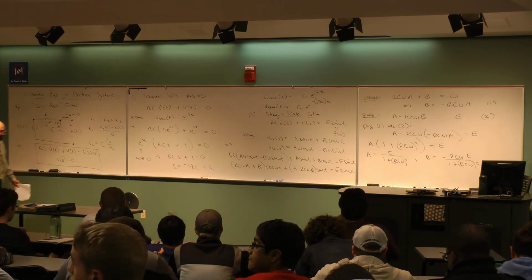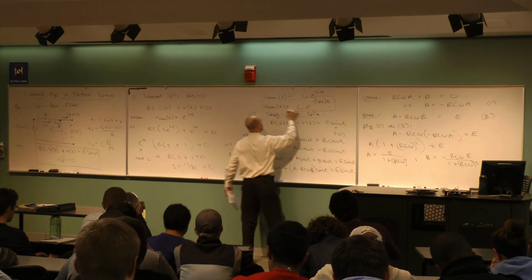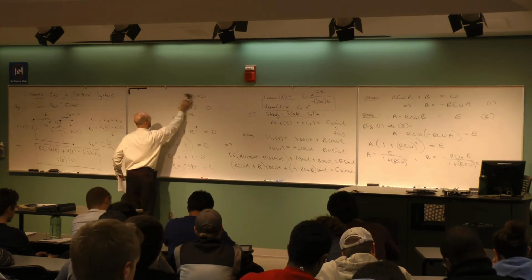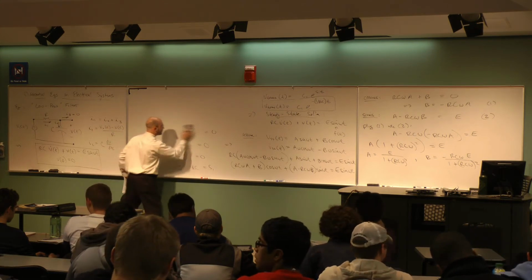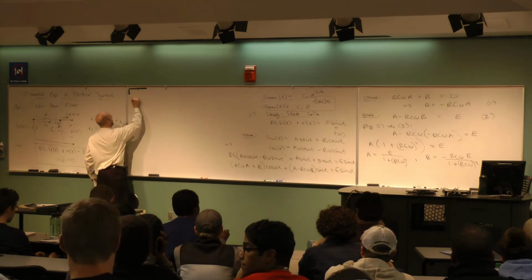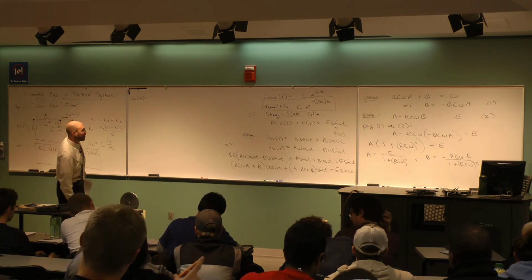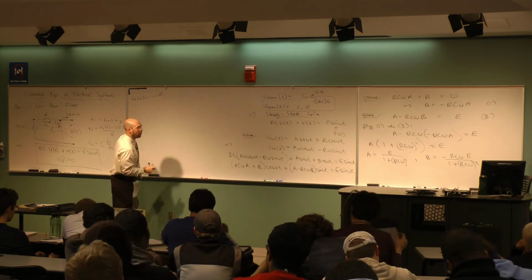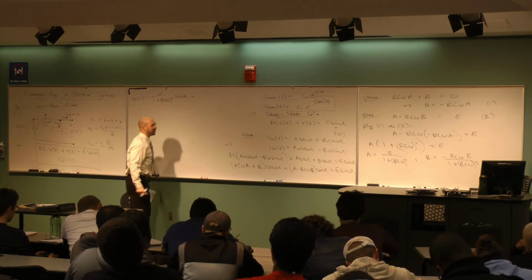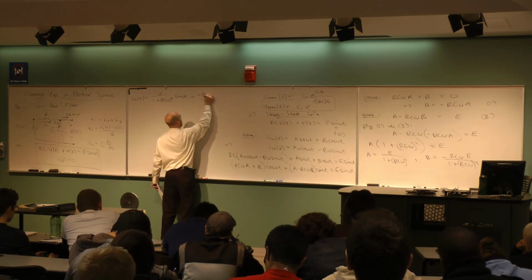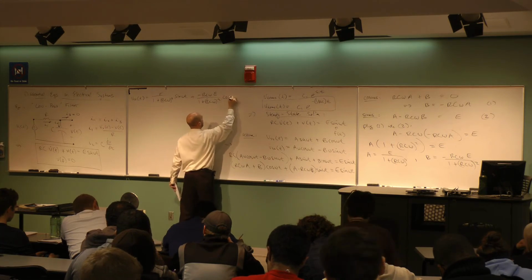Okay? So let's see. I've got A and B, so we'll come back to here, right? Transient solution. Maybe put a box so we don't forget what that was. Okay, and let's go ahead and write out now that steady state. What does that look like? So, V steady state is going to be what? I've got an A and a B, both non-zero. So it's A, that's E divided by 1 plus RC omega squared, times the sine omega t, plus I've got B times the cosine. B is negative RC omega times E divided by 1 plus RC omega squared, right, times now cosine omega t.